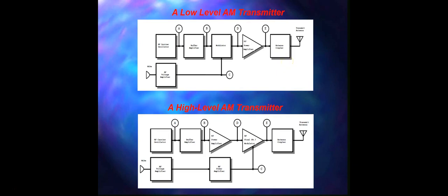It is combined with the whole block diagram, and it performs no amplification and has no active devices, but it has two important purposes. First, it is used to match the impedance, and another is it is used for filtering. Those are the two main jobs of this antenna coupler.